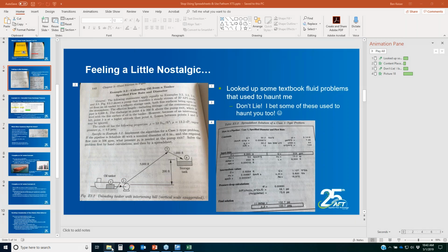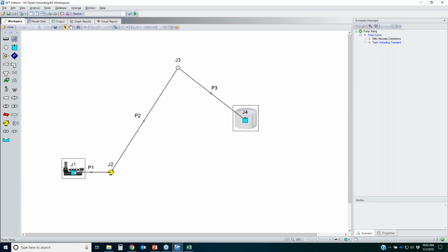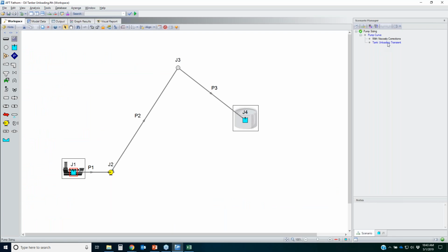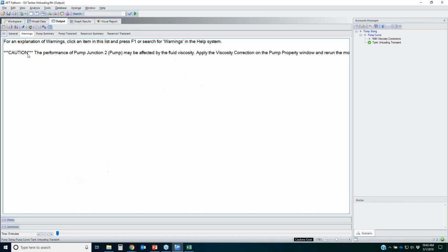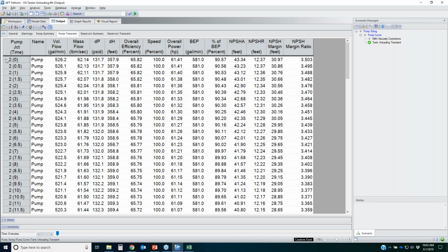So when I did the steady state pump sizing case, I based it off of 0 for the liquid height. As you can see, 0. But then when I did my transient analysis, I did my liquid height at 15 feet. So if we look at this here, it's at 15 feet. That's why we see a little bit more flow there. So this is one of the things that you would not be able to capture easily if you were just doing hand calculations or spreadsheet calculations.